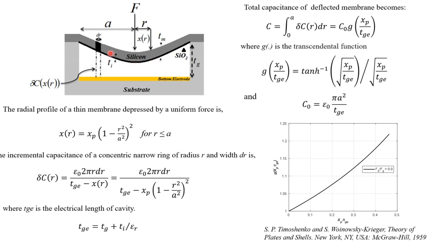Okay, which is non-linear. The profile is non-linear. It's not a parallel plate capacitor. So you cannot think of the capacitance simply in terms of the circular area, like pi a squared over the etched cavity gap height. You have to calculate the capacitance in terms of the membrane profile.